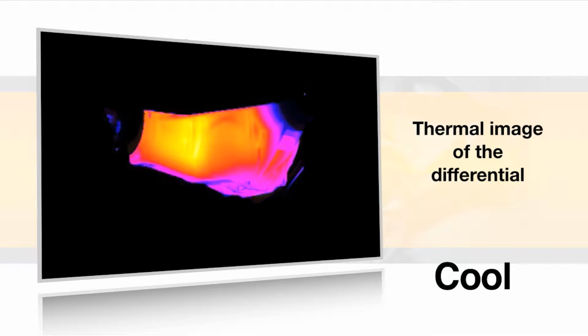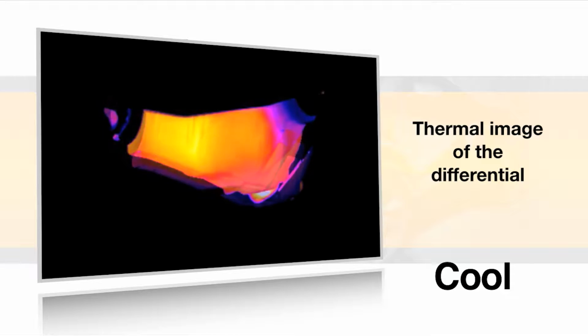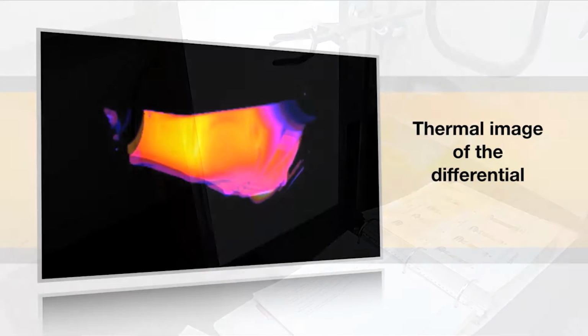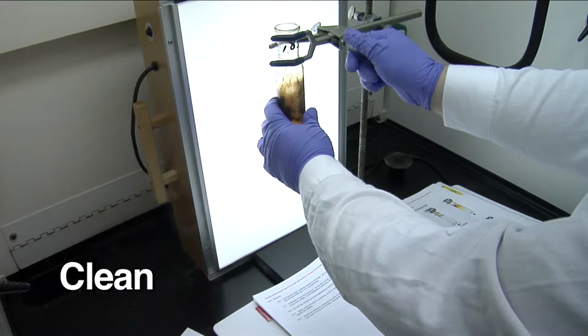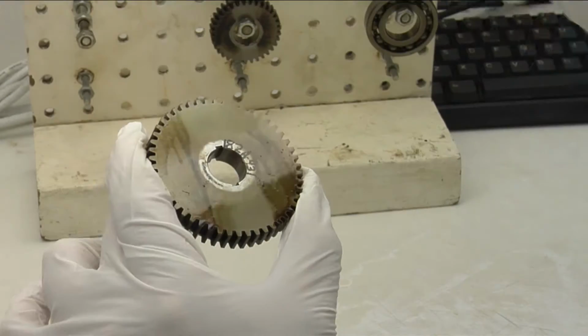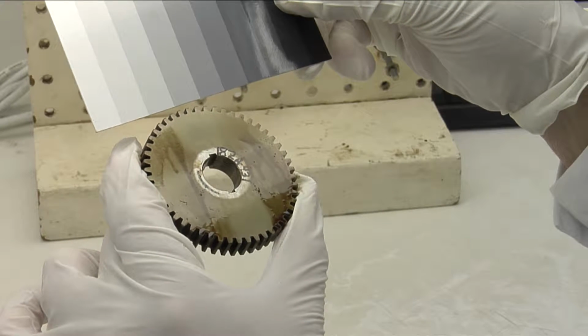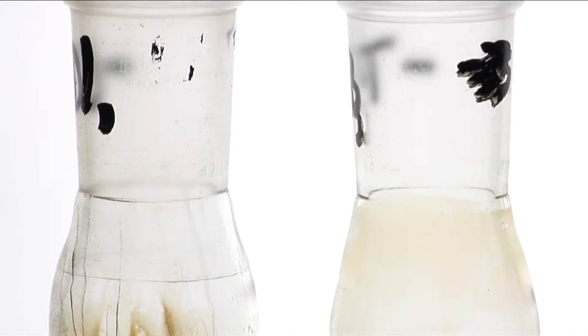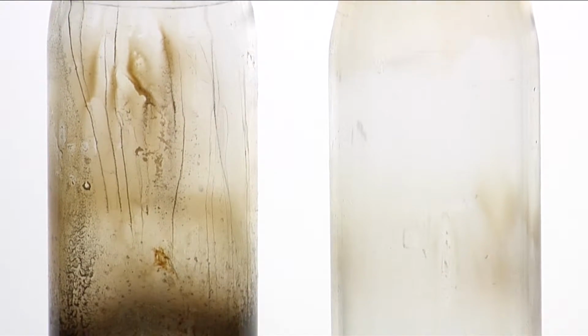They help to cool the components. As the lubricant flows around assemblies like axles, it carries the heat away and helps to dissipate it. Lubricants help to keep the components and assemblies clean, with any component debris particles or oil degradation products like carbon, sludge, or varnish being suspended in the lubricant. These contaminants can be strained out using filters, enabling the lubricant to continue to perform its cleaning function.